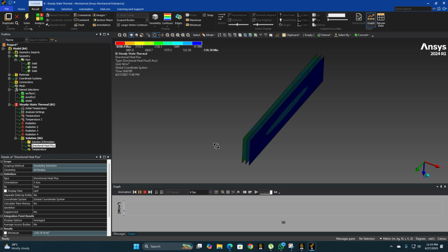See, now the maximum is 4208. Before it was much higher. So the first shield is, if the first surface is giving off the heat, the shield is protecting this shield from getting any heat flux, and most of the heat flux is in the blue range, which is of very less, -4. The negative heat flux also actually correlates to outgoing heat flux. That means this surface is now giving off heat. That is better for insulation in this whole compartment.